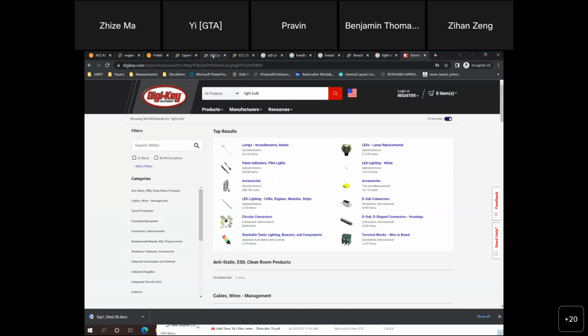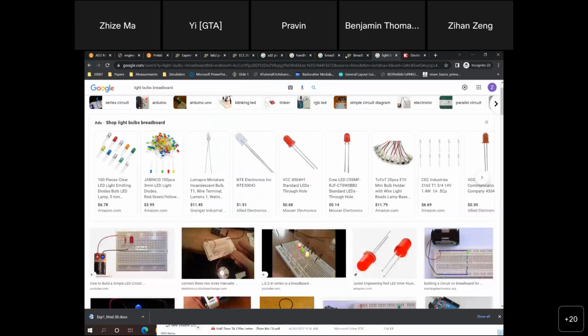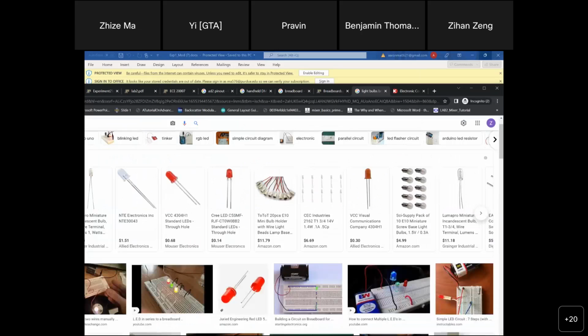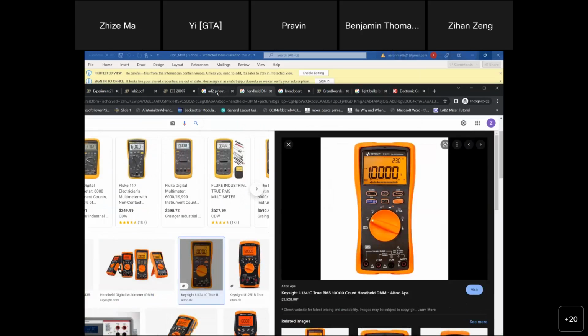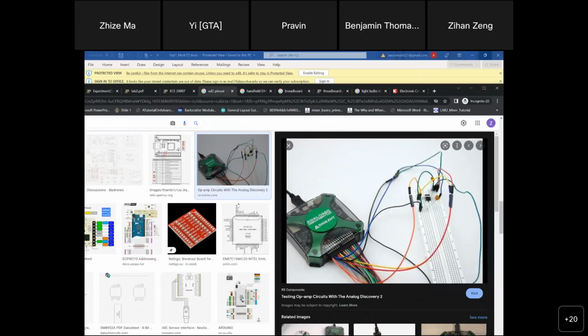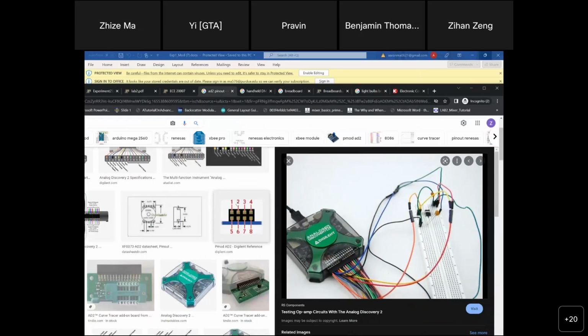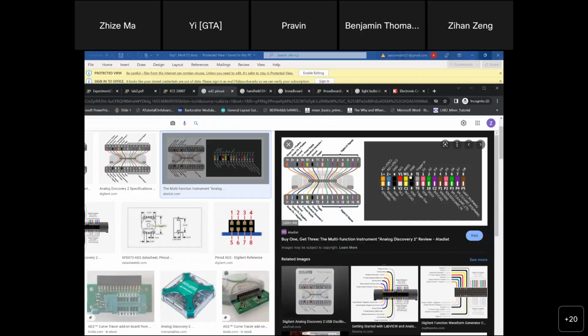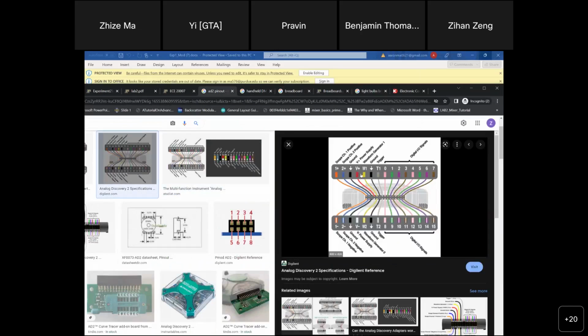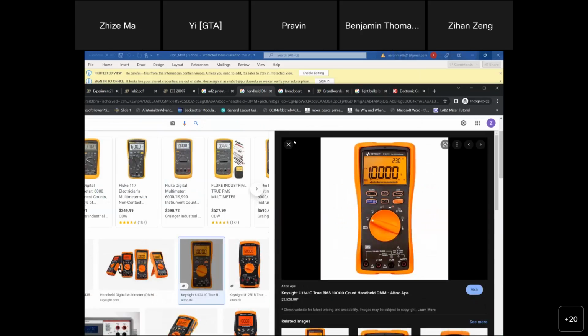If you remember, I mentioned the AC signal is coming from W1 or W2. So for example, this is the pinout. W1 is where your signal or voltage comes from, and then you need to use your handheld DMM to measure it.